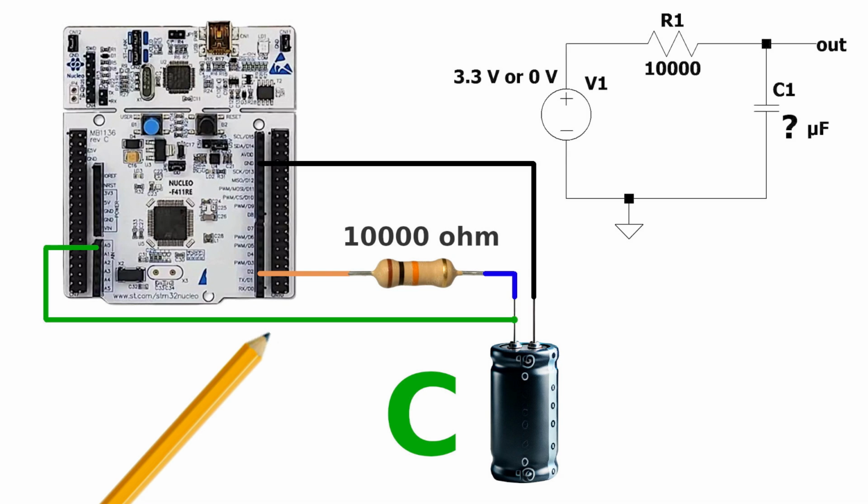Digital pin D2 is set to low to guarantee the capacitor begins at a specified voltage level, therefore providing a connection to GND and discharging the capacitor to 1 volt. D2 turns to high once depleted to start the charging process. The board tracks the capacitor's time to reach 2 volts.